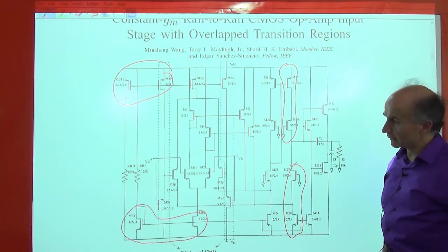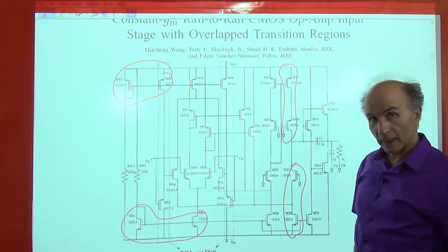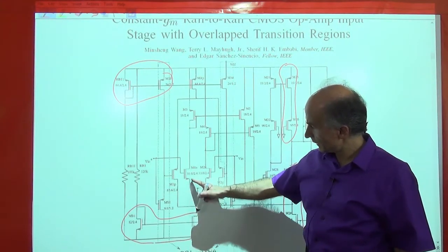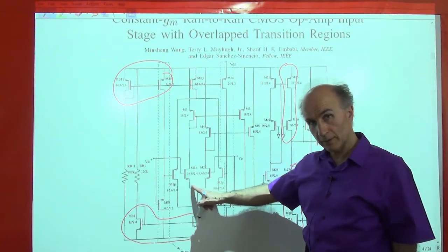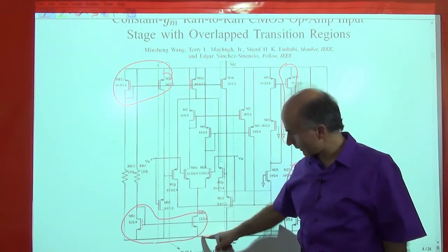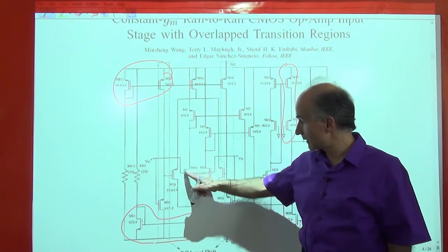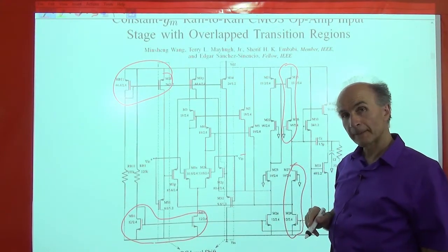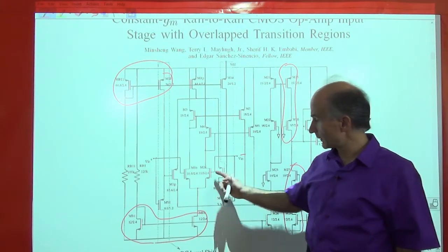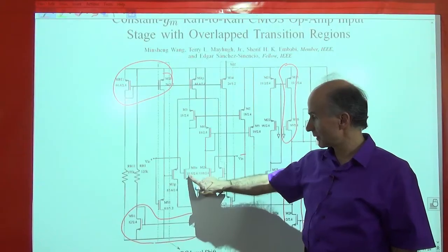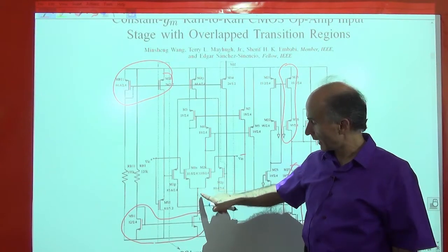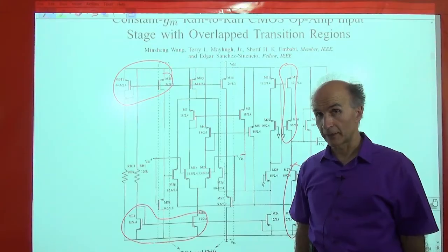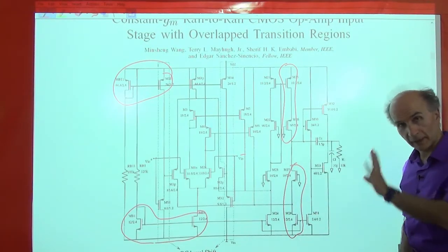Now there's another structure here that is curious and intriguing, but we have not studied. Look at these two transistors. You see, their sources are attached to each other, and there is a current source down here. And they have two gates connected to Vin plus and Vin minus. Okay? So that's an interesting circuit, right? It's symmetric. Two NMOS devices, they have the same dimensions. You can even see the dimensions of the transistors. And there's a current source on the bottom. So what is this? We will have to see. This is actually what we call a differential pair. So we don't know what it does and why it's here, but at least we can see something.